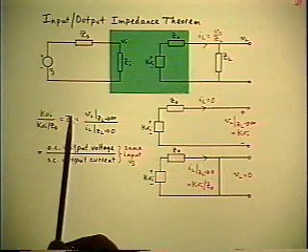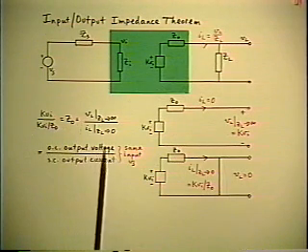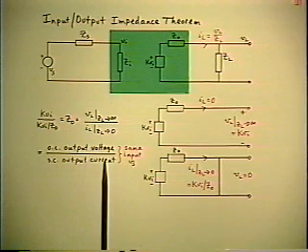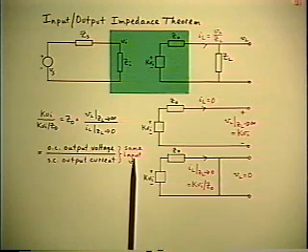Because this sort of interpretation that we've just gone through, limiting the output to be open circuit voltage or short circuit current, well, this is what you'd expect. So there's nothing new there. But there's one little extension. That's all we need. The output impedance is open circuit output voltage over short circuit output current for the same input voltage. That's a necessary condition for that to be true.